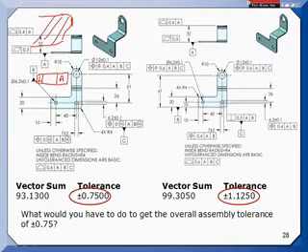And so what happens is people will put perpendicularity on a feature like this, and then the supplier, when they're trying to get through their first article inspection, keeps getting rejected because they can't gather enough data to prove it's good. There's no way for it to be bad. So a little common sense kicks in here. You don't want it to go too far, but on something like this, I wouldn't probably put a perpendicularity on it. Technically, it should be there.